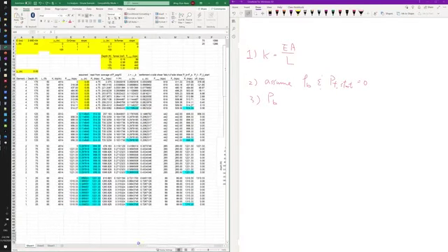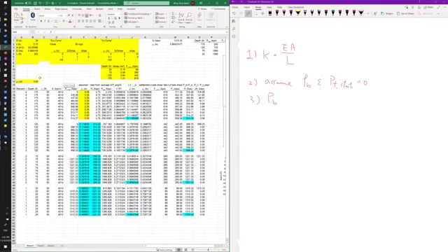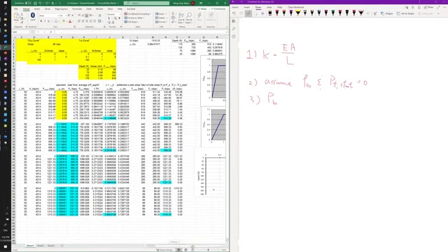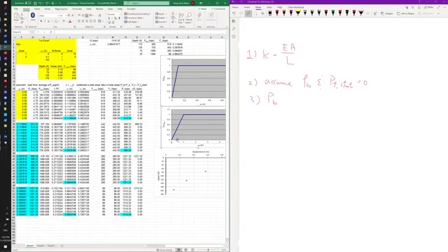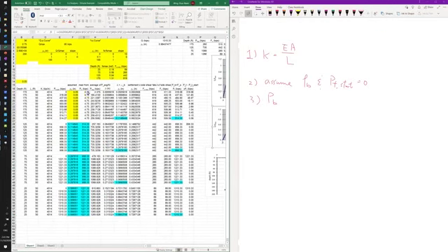We find 0.05 inch, and then we go to this curve. Whatever we read will be my Q values based on this displacement. It's just read off this curve, and then you need to multiply by the Qmax.